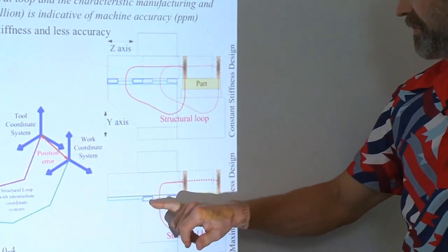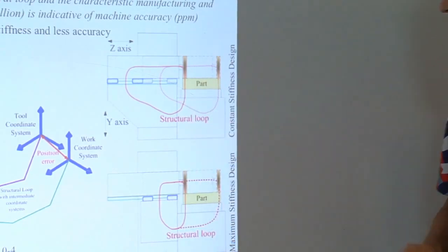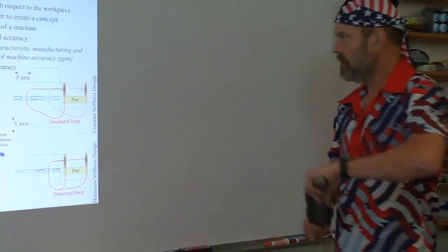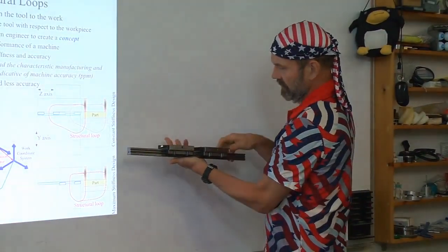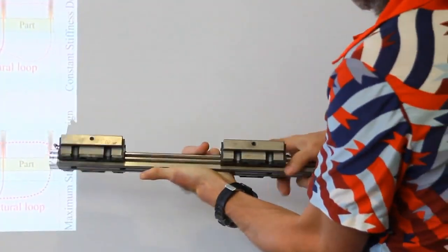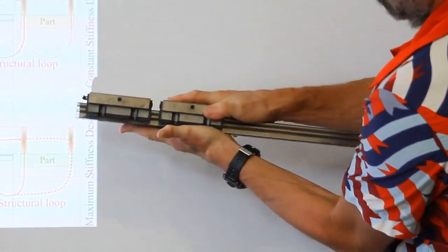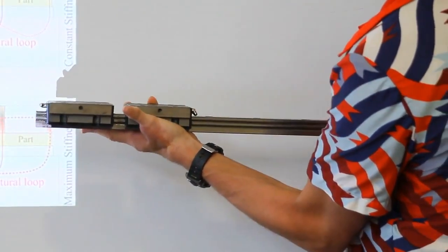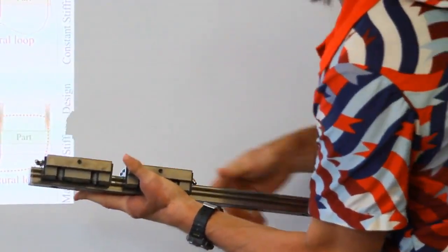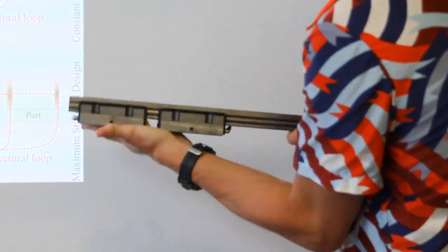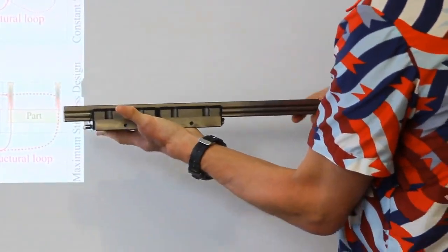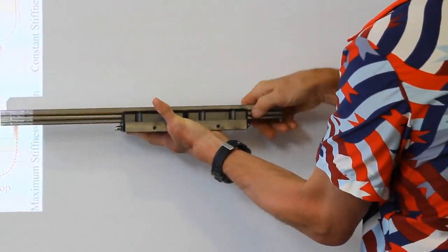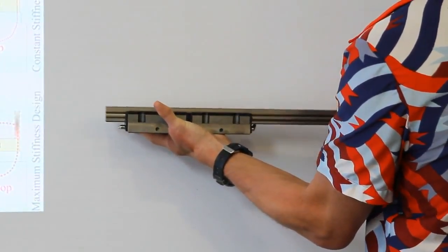But a very, very subtle difference between the 2. On the top machine, the bearing rail is fixed, and the z-axis would move along the rails like this. Excuse me for only moving one of the bearing rails. On the bottom machine, it's flipped. The carriages are attached, so the z-axis moves up and down, or the y-axis that moves up and down, and the z-axis moves in and out.